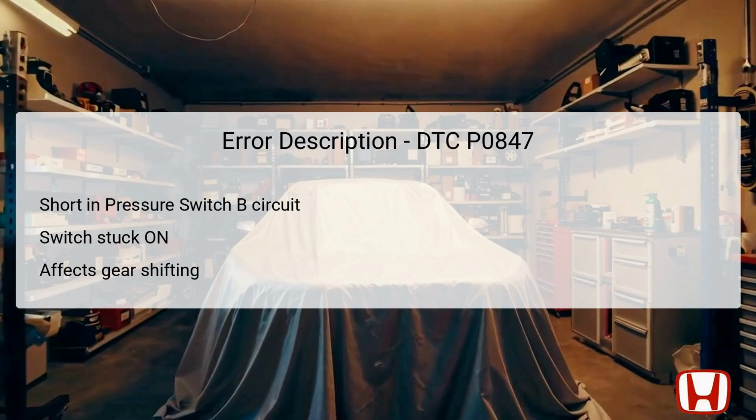If this switch fails, it results in the vehicle being locked in certain gears, specifically only allowing shift to third or sixth gears due to the fail-safe mechanism. The placement of this switch is integral to the transmission assembly, usually located near the clutches, which means access may require removing certain components for inspection. This issue does not stem from mechanical transmission problems, but indicates an electrical circuit malfunction.